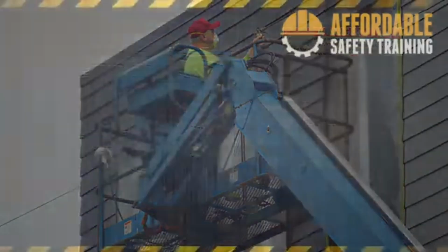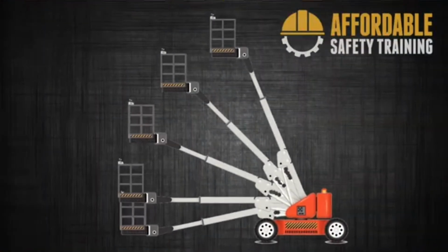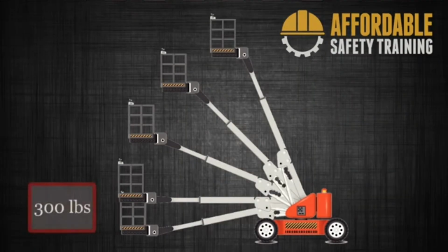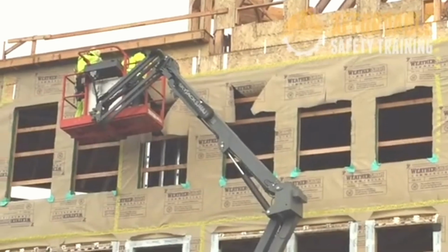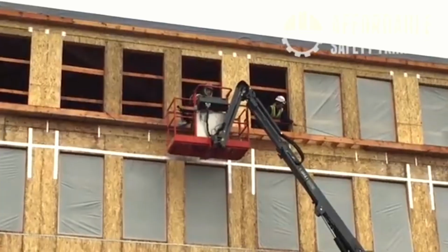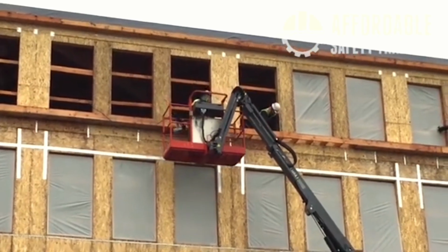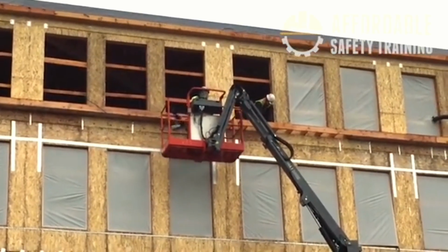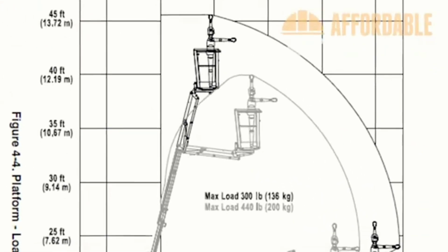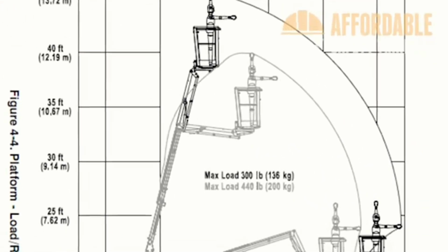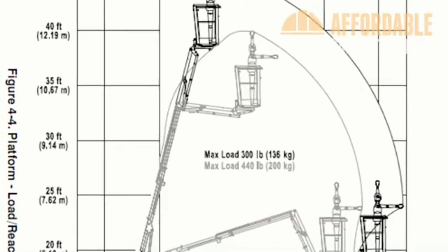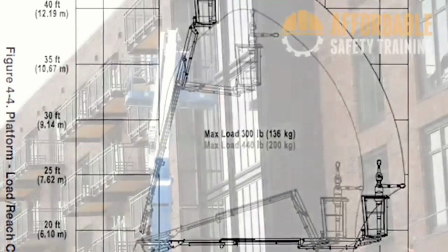The lift capacity can vary, depending on the position of the boom. An extensible boom lift, with the boom fully extended and lowered, may have a lower capacity than one that is straight up and down. Most lifts have one maximum capacity listed. If you keep the load on the platform lower than this maximum load, you will stay within the capacity limit in all boom positions. It is critically important that you know the maximum lift capacity of the aerial device. Your life depends on it.